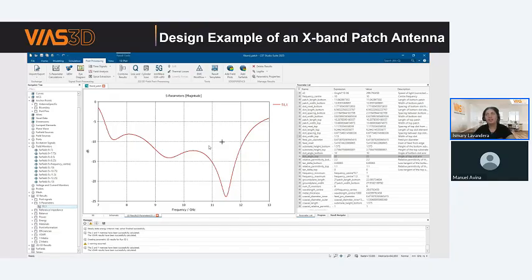Here is already giving you some recommendation. My tips: check the width, check the slot angle, check this, and it will improve this parameter. And also at the end on CST, you can change everything because everything is already parameterized. So let us continue